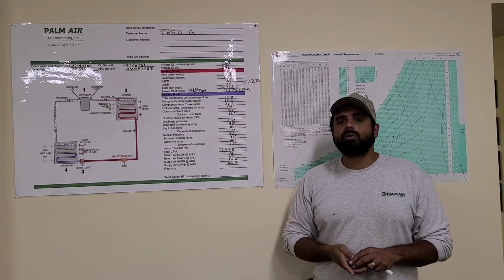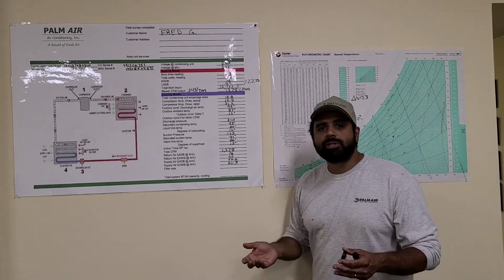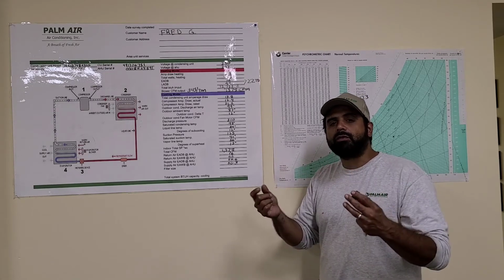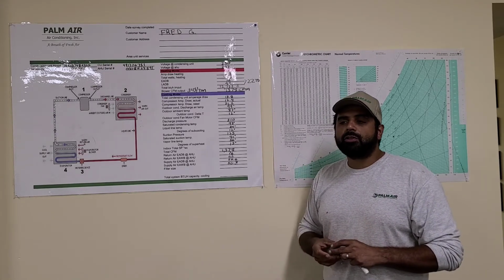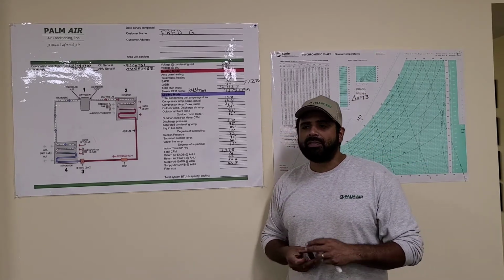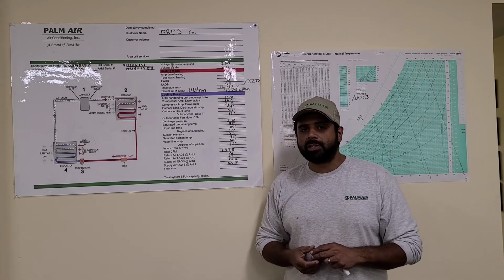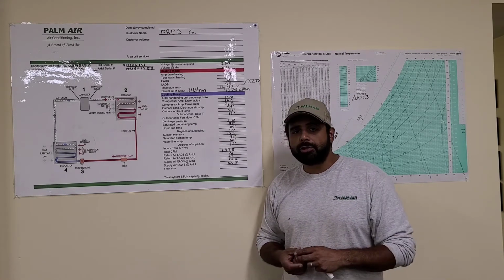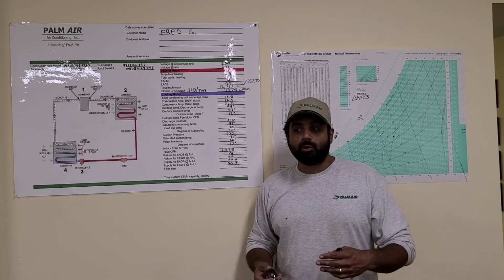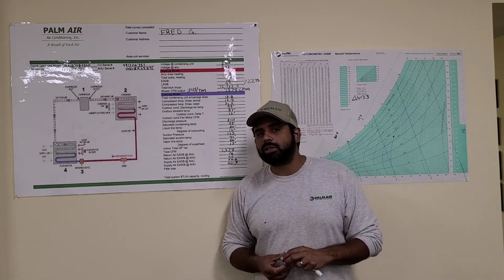And just so you guys know as well, not everyone has these out in the field, and it can be a little cumbersome. Plus, when these are smaller, they're even more difficult to follow with your eyes. There's plenty of psychrometric calculators out there in app form. I think the one I'm using is called Psychrometric Light or Air Light Psychrometric Calculator. Basically, you plug in your altitude wherever you happen to be. We're in Boca Raton. We're basically sea level. I think our official altitude is 13 feet.